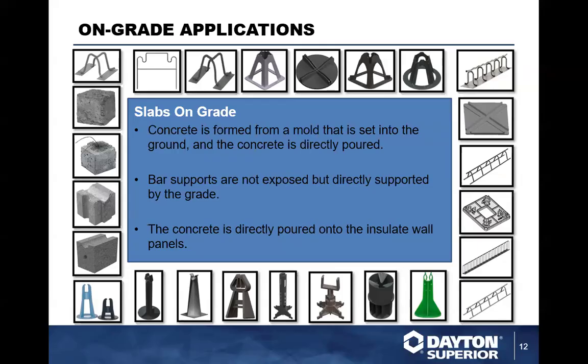A concrete dobie is, for lack of a better term, a concrete block. It is shale and cement mixed together to create a reinforcement component. I would recommend it for slab on grade only, primarily because these are shale and cement, and when they're cured, they're very dry.